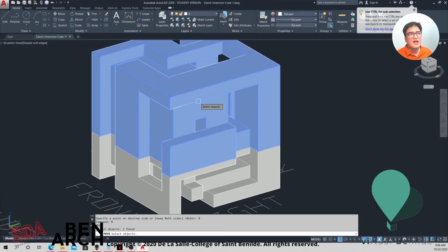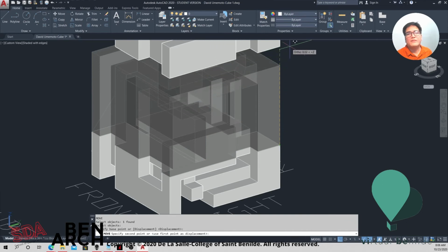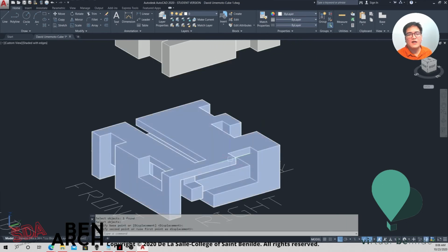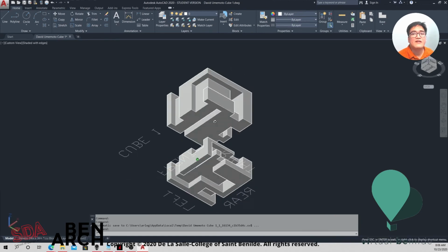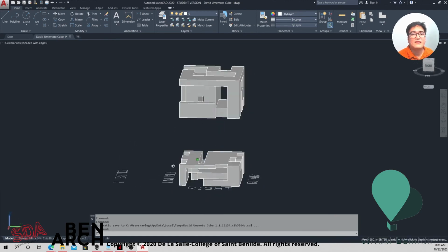Okay, I'm going to choose the upper part, enter once, and I'm going to click anywhere, or probably I need a pick point somewhere there. Then I can lift it up and you can see the outline of where that level of 3.5 is going to cut. Now you can go and, of course, take a look at the underneath and whatnot.